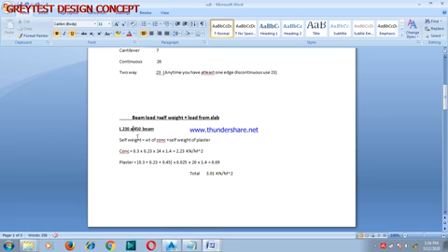That means whenever the dimension or the thickness of this beam changes or reduces, you cannot use 3.01. What I'm trying to explain is that this value is not always a constant. You only use it for a 230 by 450 beam.